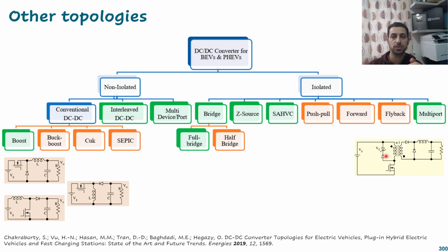And that switch has to pulsate the input primary side here just to make the current alternating, and that can be really amplified at the secondary side and rectified here to get the DC current again. So it's like DC to AC to DC again, okay? And that one is very, very popular. There is another similar one, which is the forward. It's very similar to the flyback, but it has some small differences.